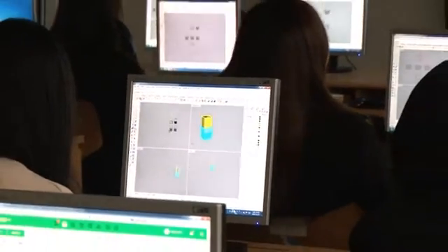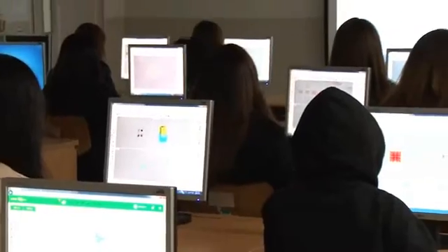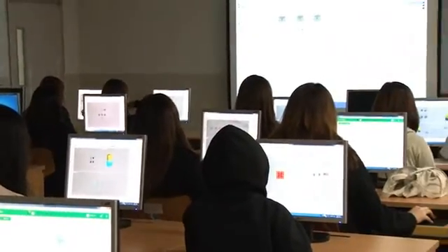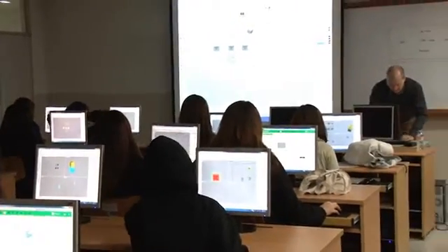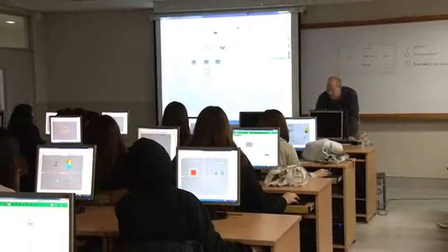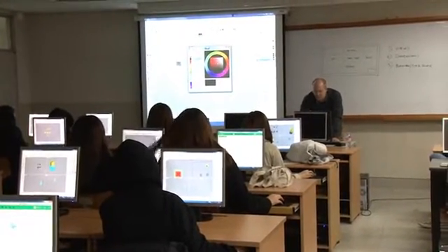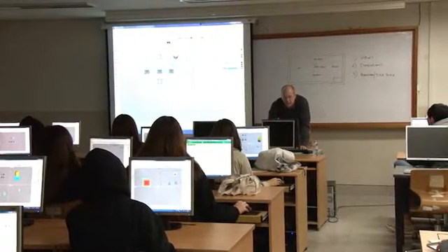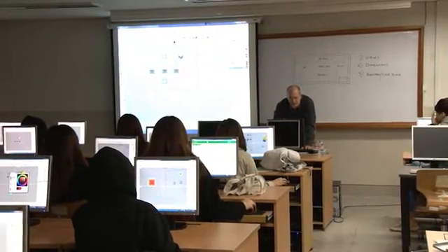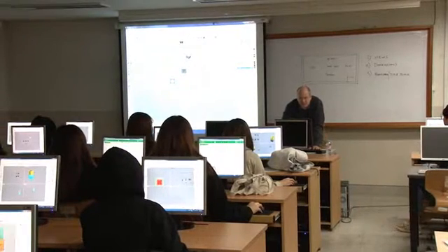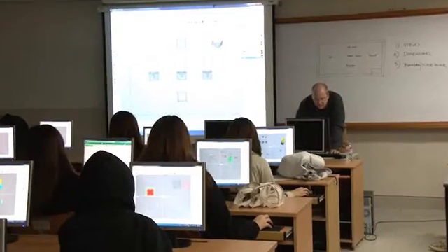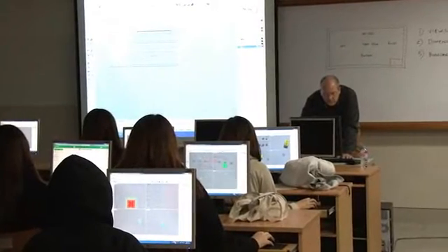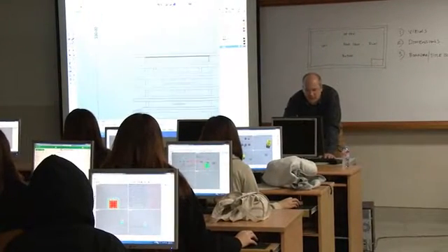Now let's create some general dimensions, some overall dimensions. Okay, so let's create a new layer called dims, and since we like dimensions nice and bright, let's change color to red. And let's make sure that our precision is carried through. So dimension linear, this should be 330. Perfect, right? We like that.